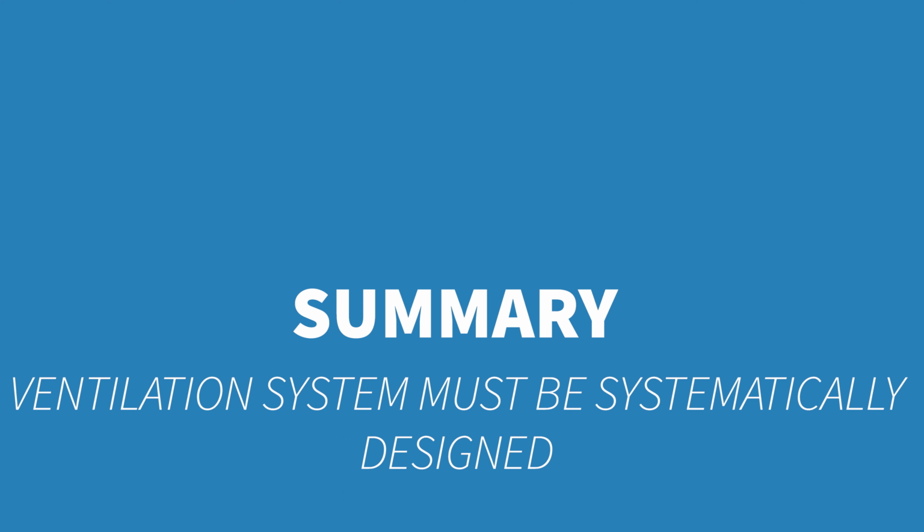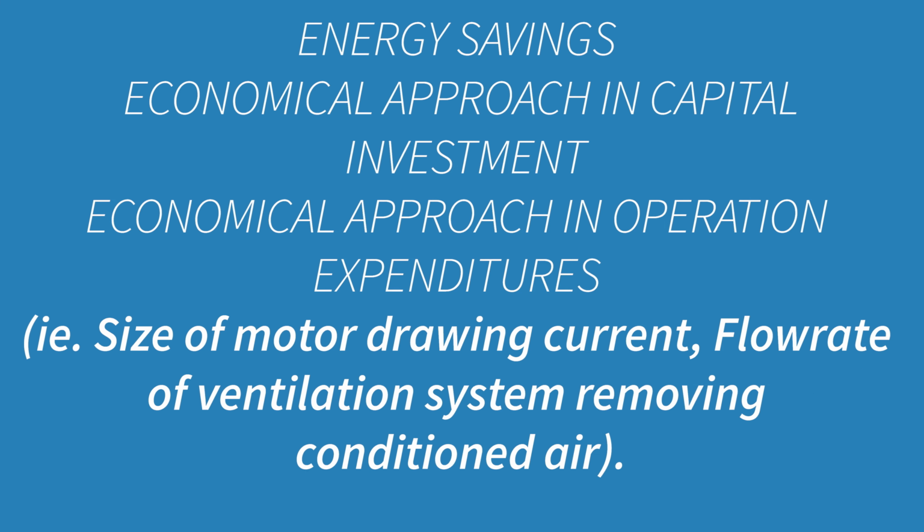Another important element which always gets bypassed is the importance of saving energy. You do not want to size up a very big fan. There is a mentality that big ventilation and a high flow rate is better. No, it's not. You do not need a high flow rate. You do not need a big, high-velocity system.